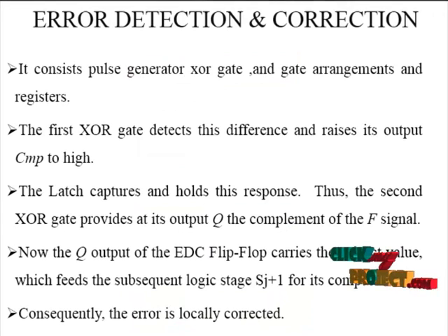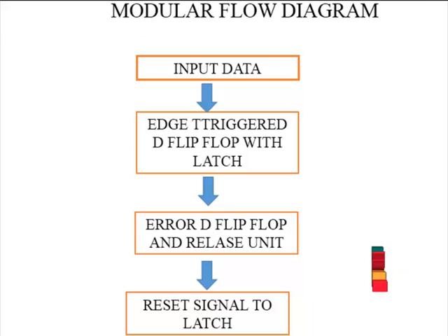After that, the process is fed into the latch. The T latch, or transparent latch, is a simple extension of the gated SR latch that removes the possibility of invalid input states. Since the gated SR latch allows us to latch the output without using the S or R inputs, we can remove one of the inputs by driving both the set and reset inputs with a complementary driver. We remove one input and automatically make it the inverse of the remaining input.